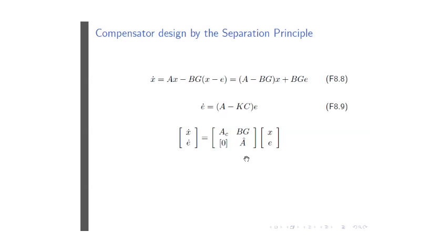Now, this is actually true that the moment I connect the observer and the plant with a control law that I'm using, if I have a full state observer, I'm actually doubling the order of the whole system. In other words, if my plant was 4th order and I use a full order observer, I now have an 8th order dynamic system that I'm operating, if I can call it that. My whole control system, plant and observer, is then 8th order. And that is quite clearly reflected by what I'm doing here. My new A matrix is this matrix, and it's 8 by 8.